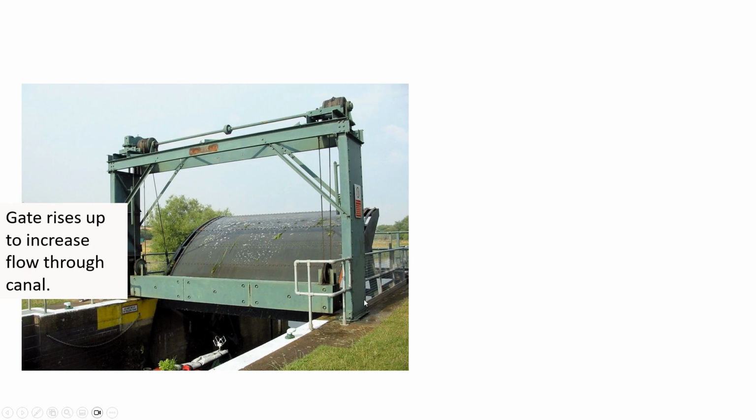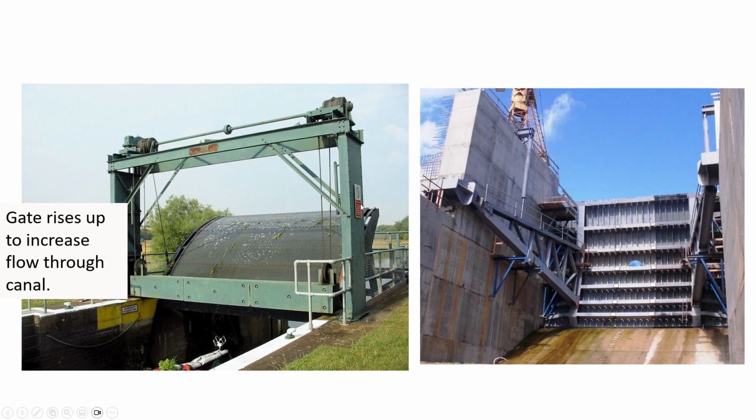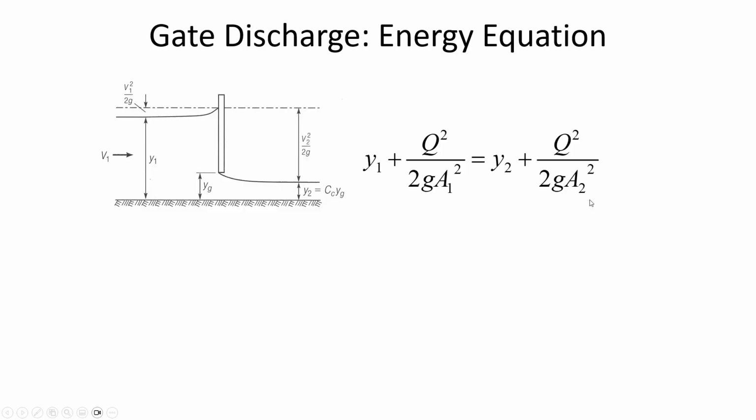So a gate like this, if it's curved in shape, so you can kind of get a sense for its curved shape, and the forces act through a central axis. And so the hydrostatic pressure and the hydrostatic forces aren't adding to the force required to lift the gate if you have a central axis that all of the forces act through. It's just the weight of the gate that has to be lifted if you take this approach and have the curvature on it.